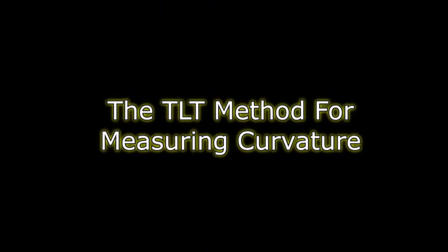The TLT method for measuring curvature. Terrestrial laser targeting is designed to be a curvature surveying method over long distances. The idea is to prove a straight line on a surface between 2 points by shooting the laser to the target location and verifying the height of the beam at each side.